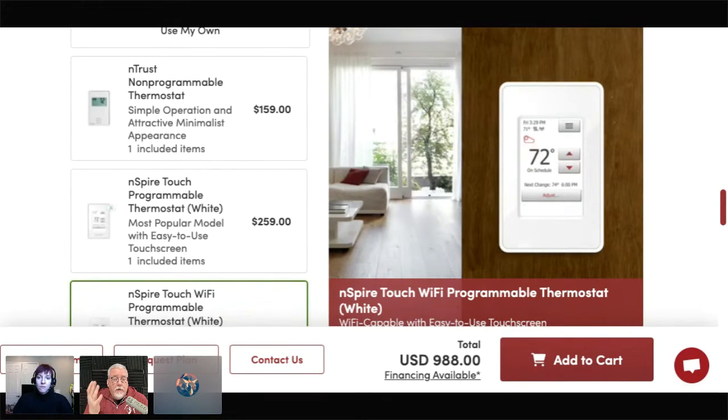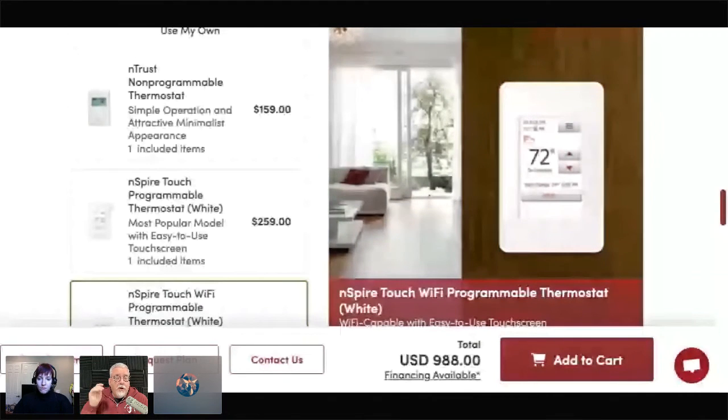Some manufacturers of engineered flooring or laminate will say, no, you can't have a temperature swing of more than 3 degrees every day. Well, that would mean you'd go from 85 down to 82. That's as much as you can. There's no setback allowed. So that's going to also help you choose your thermostat, because that first one right there, you see the Entrust non-programmable thermostat. That's the one where you set it at a temperature and you keep it there. That's what a lot of hardwood flooring people require. No setbacks, raise it 2 or 3 degrees a day, and that's it. So there's no need to buy a programmable thermostat because you can't program it. It has to be set to a temperature and kept there the whole time.